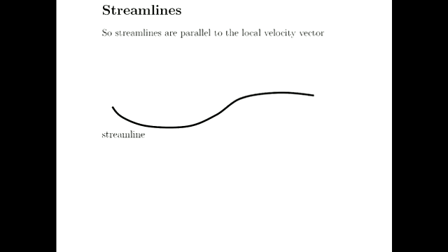So there's this streamline, and we want to derive an equation for that streamline in terms of the velocity components. And it's very simple. I can take some element on that streamline, ds, okay, and we know from our definition of a streamline that that element ds must be tangential to the local velocity vector, which I'm going to call V, okay, and I'm writing this out in vector notation.